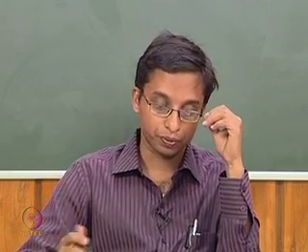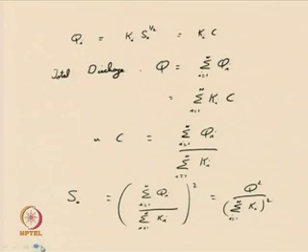You will be able to get the bed slope of the channel directly for the compound section. You just need the channel properties. If you have the conveyance factor for each of the subsections, based on that you are able to compute the bed slope also. You can see that as a homework. You can just think of doing the following problem.